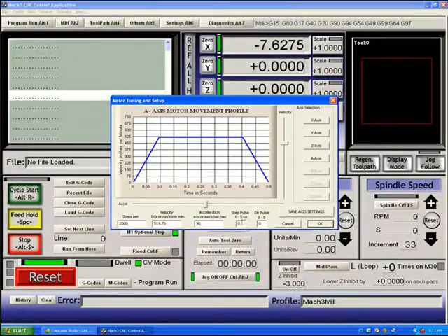If for whatever reason you find that your motors are not moving when you're using your up and down arrow keys, or they sound bad, you can use these numbers to increase between 0 and 5 the step pulse width or the direction pulse width. The only time you'll change a direction pulse width is if you find that you're losing 1 step each time you change direction. For 99% of users, you will never change this above 0. For 90% of users, you will never increase the step pulse above 0. Some controllers, however, do require up to 5 microseconds of additional step pulse width because the optocouplers in the drivers are a little slow, and this gives those optocouplers a longer time to adjust.